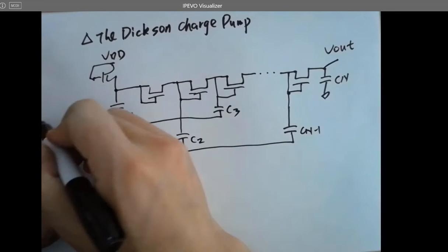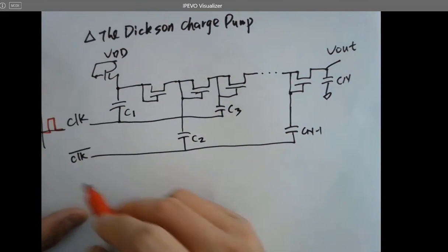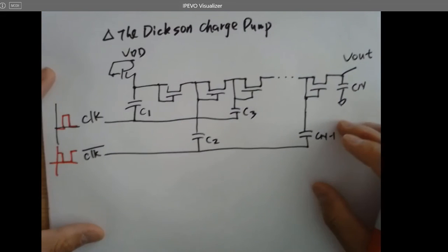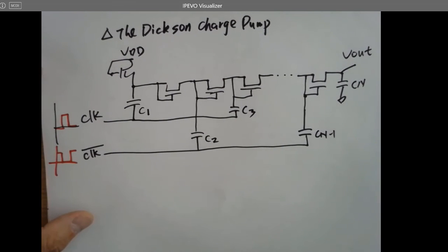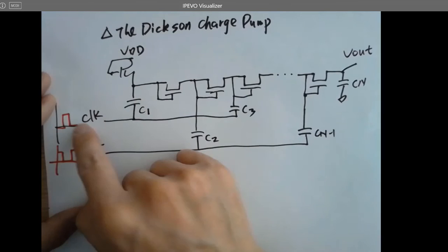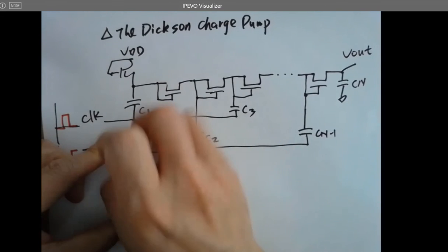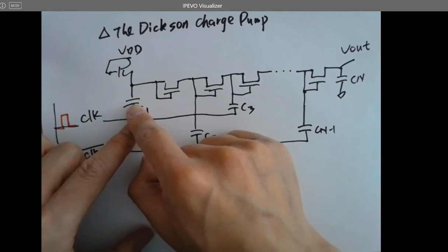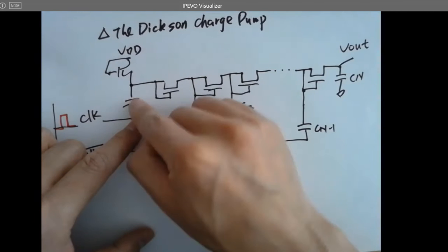So clock is definitely, there's no negative voltage for clocks, right? Again, this is the inverted clock, just inverted using the inverter. So whenever this is 0, what's happening for this cap? It pulls current, it just pulls charges from this side of the plate, which will pull charges from VDD to here. So it's going to charge up the cap.